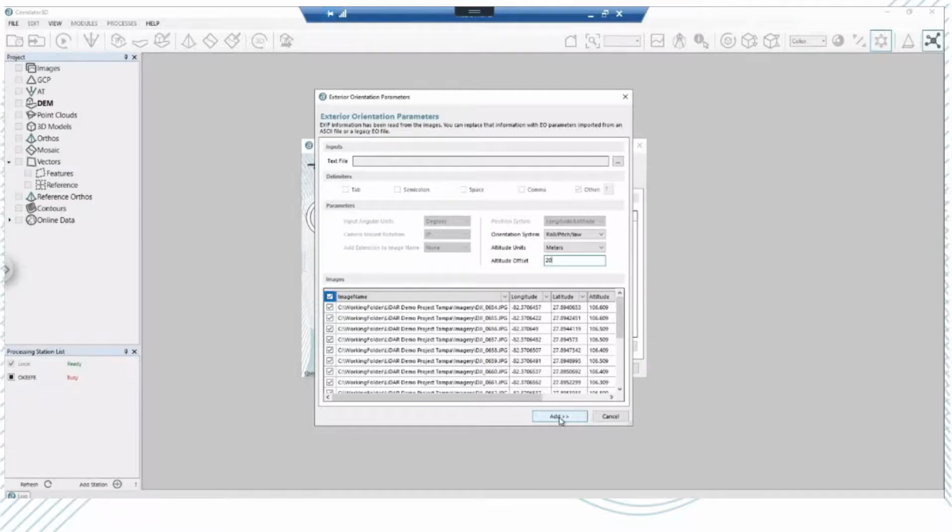So that's what it's doing to make that correction. And if you weren't to do that and you were to run it RTK, PPK assisted and process out the dataset, you'd probably see a consistent vertical error. Anytime you see a consistent vertical error, then you're probably off in your geoid/ellipsoid adjustment. So just to keep that in mind.